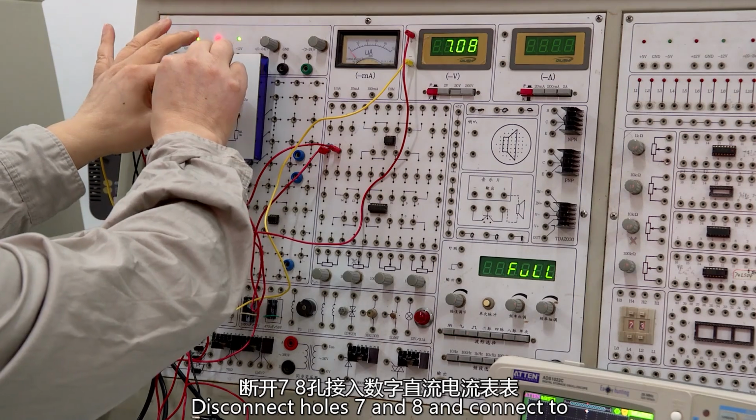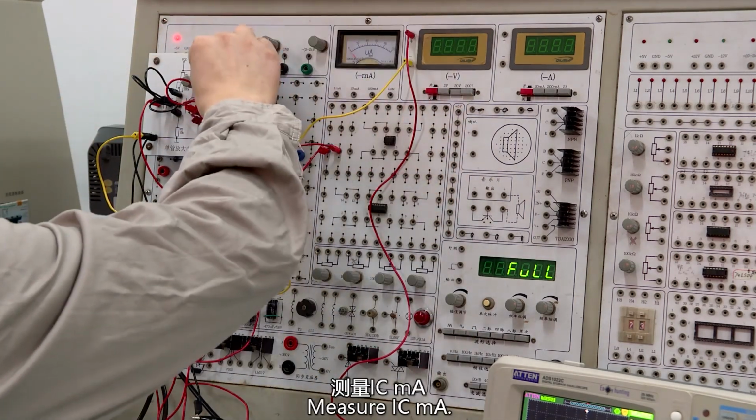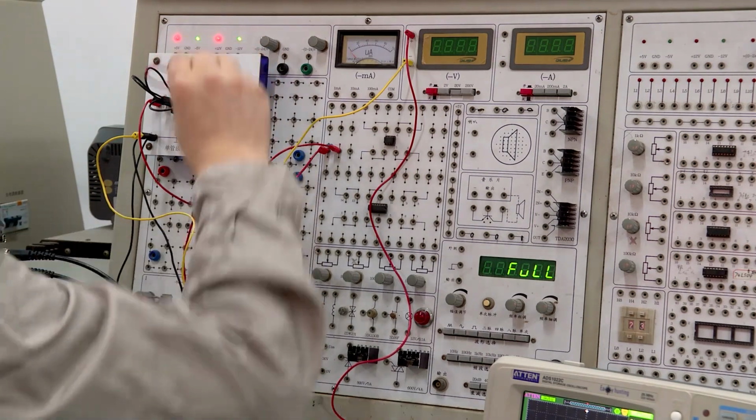Disconnect holes 7 and 8 and connect a digital direct current milliammeter. Measure IC in mA. Record in the table.